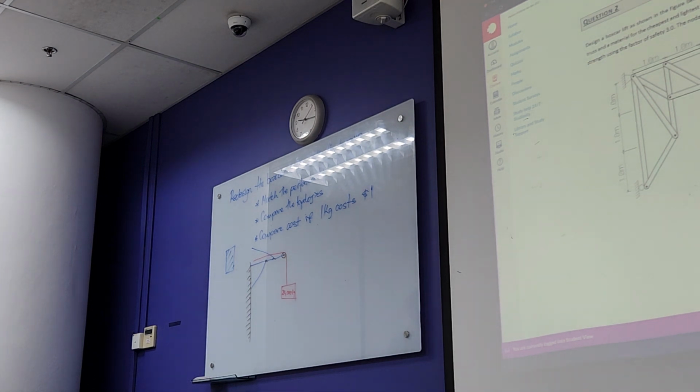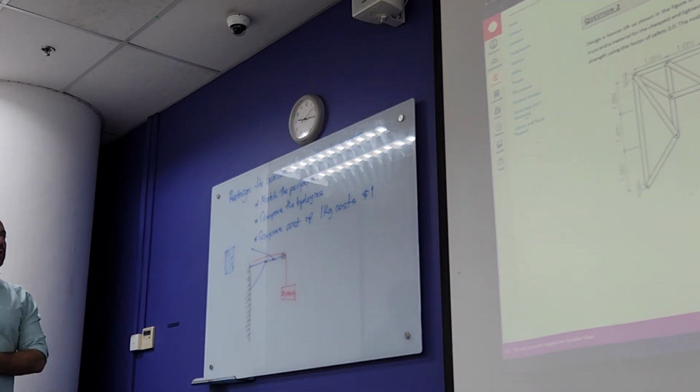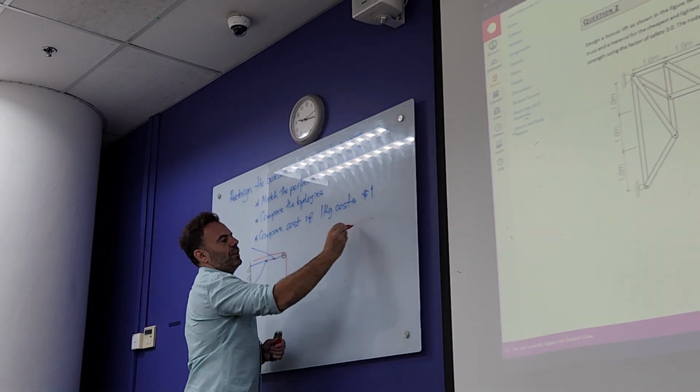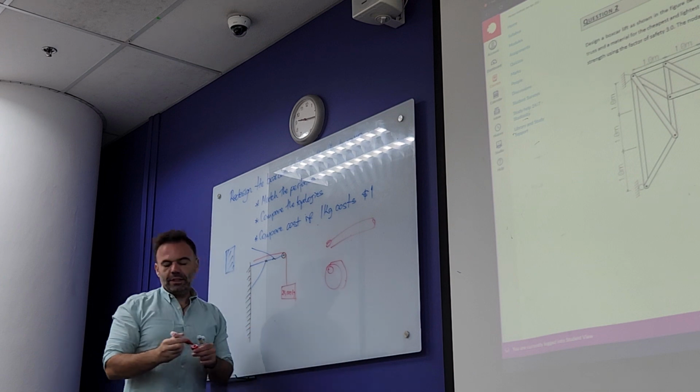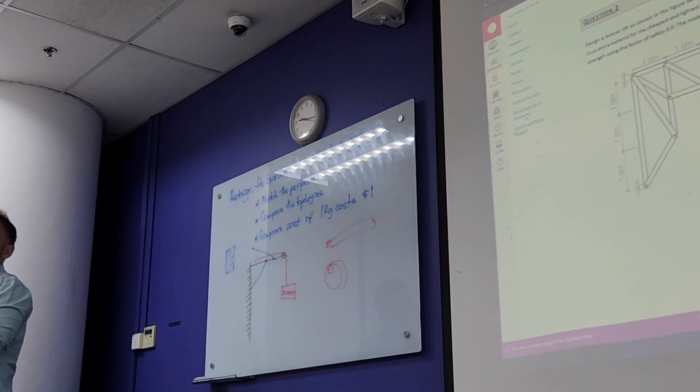Yeah? Same goes with the beams. That story, remember that story of having beam or having coin. That will be also something on a test. If you make beam elements too short compared to cross section, again, it's your failure as FEA engineer, not modeling that right. So small things like that. That's what we're going to look for in your submissions. Yeah.